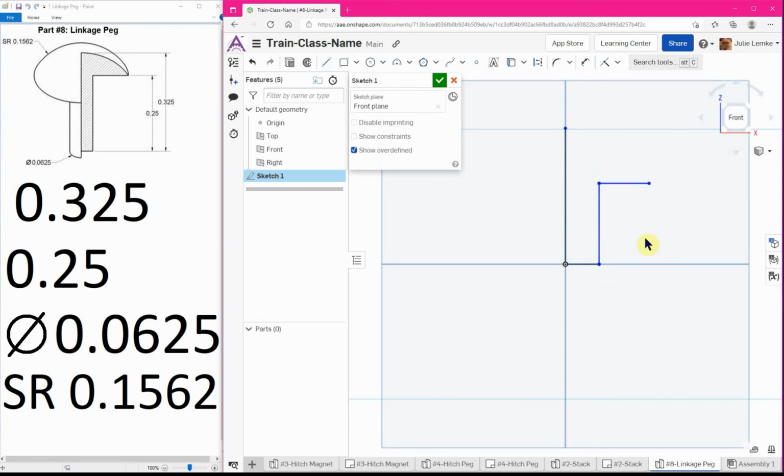Okay. So basically what I did in one shot is I drew all the lines, the straight lines for our shape, except for the curve. So when you add this line in, make sure you go down to the origin. So then you can see that some lines are turning black, some are still that bright blue. Just so then when you start dimensioning, you know if everything's locked down in place. You want to make sure it connects to the origin.